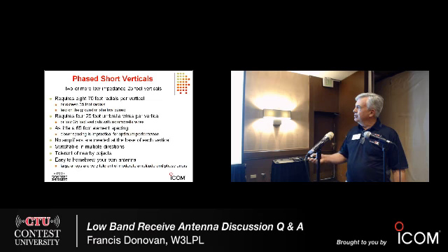Or you could use a larger number of short radials. The version that I use uses 4 25-foot umbrella wires. I'll show you a photograph of the antenna a little bit later. It's really simple. Joel's website shows practical details, W3LPL.org. If you don't have room for the umbrella wires, you could lengthen the height of the verticals to about 35 feet, and you don't need the umbrella wires. The performance is only very slightly degraded.